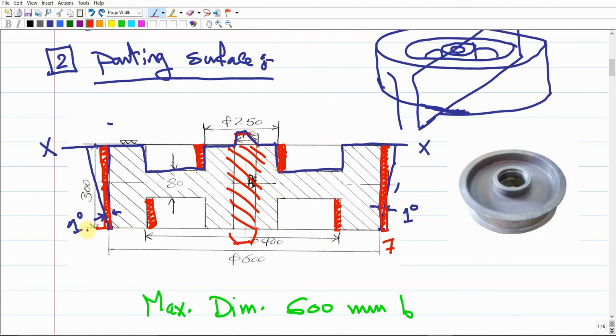So what does it mean? It means that for the 300, I'm going to build over the surface. The surface should be thicker, or something built over the surface. If we do machining, we have to remove this part. When this part is removed, we're gonna end up with a cleaner surface of the final product. So something should be built up over this surface, and this something should be 10 millimeter. This 10 millimeter definitely will increase the 300. The 300 will not start from here, it will start from above with 10 millimeters, so it's gonna be 300 plus 10.